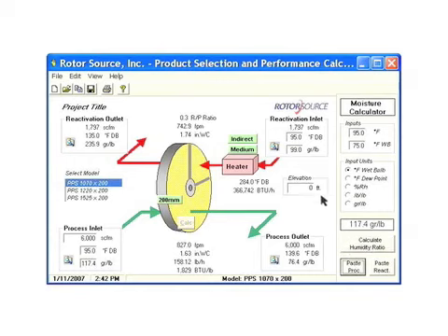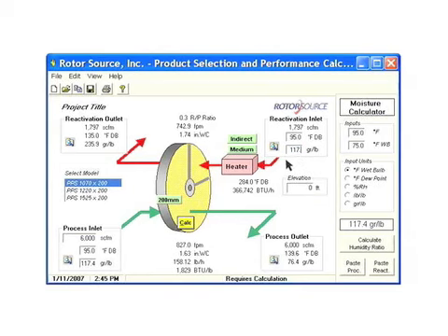You can also change the air used for reactivation to make sure that you adequately represent the amount of moisture which is used. Once you've made a selection, you can also choose to use a high value of heat, which raises the heat and temperature, reduces the moisture, or you can choose to use a low value of heat, in this case 248 degrees, which gives a lesser dehumidification.